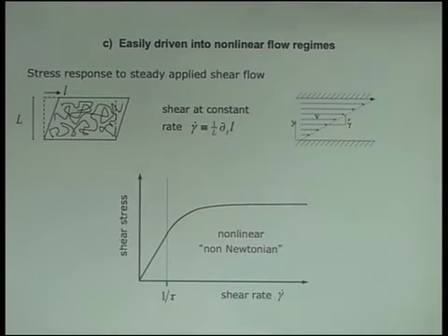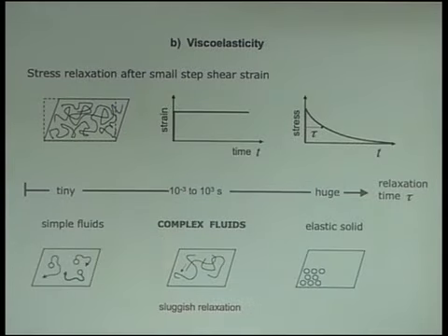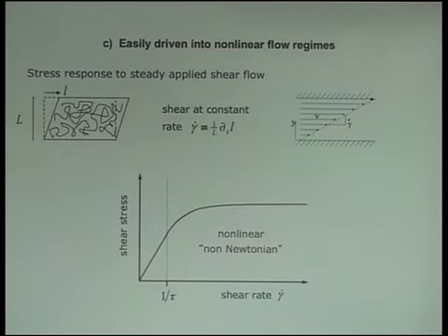And then typically we see two distinct regimes in that flow curve, depending on whether the shear rate that we're applying is either slow or fast compared to the intrinsic rate of the material stress relaxation as measured in this linear response measurement here. If we're shearing at a very slow flow rate, the material's intrinsic Brownian reconfiguration dynamics of these long chain-like molecules, for example, is fast on the timescale that we're applying strain. So in other words, we're effectively just riding along on Brownian dynamics that are already there. We see a regime of linear response in which the stress is linearly related to the shear rate, the slope being the viscosity.